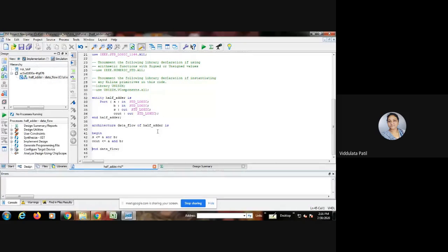If it is a vector, then instead of considering it as a bit vector, it will consider it as std_logic_vector. Whenever we consider the bit type, it will take only two values, 0 or 1, but for other values it will not say which type it is. But whenever we talk about std_logic, it will take 9 different values. So that means don't care, tri-state, all these different values will be considered whenever we use std_logic. So this is the program which we have written for the half adder.